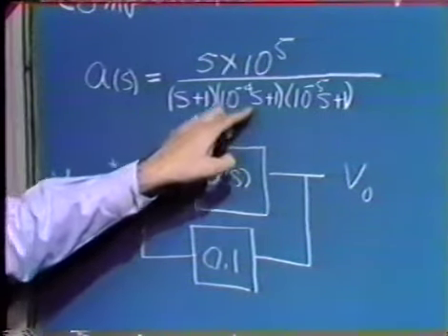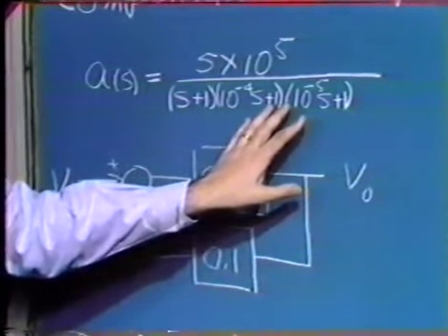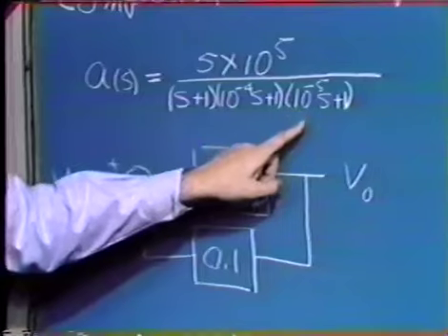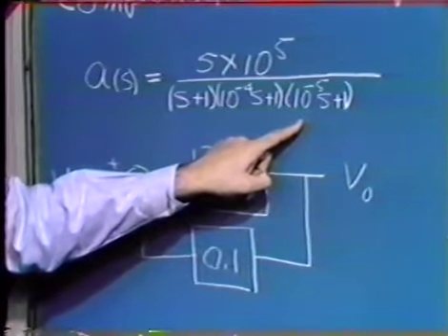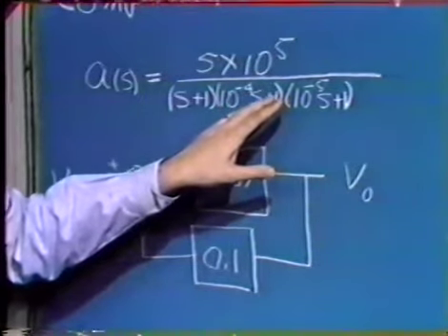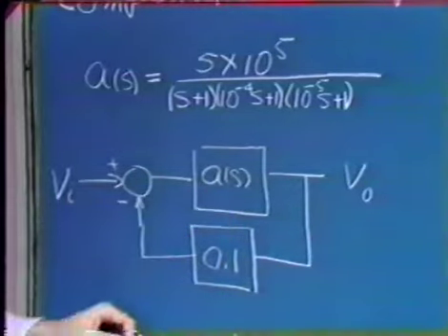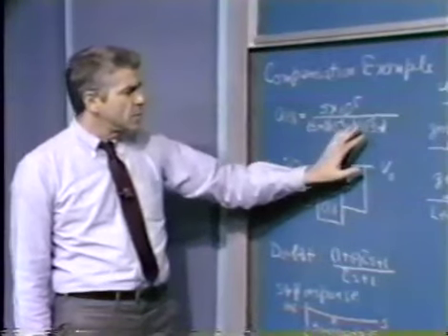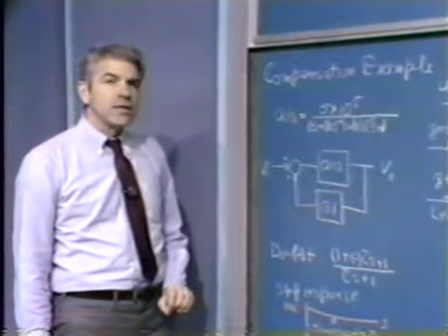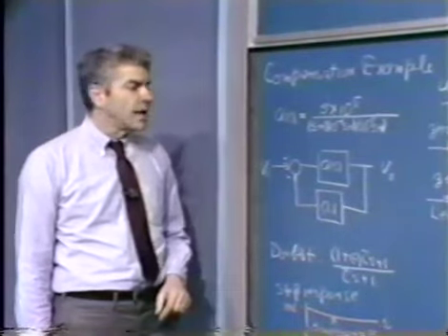However, there's then something at high frequencies that comes in that begins to deteriorate the system, and in particular gives you additional negative phase shift. It may be several additional poles, as I'm considering in this example. It may be, for example, time delays. When you look at certain kinds of transistors, you find out that they have a time delay associated with propagation of diffusion time delay. But anyway, these higher frequency dynamics give us additional negative phase shift and are ultimately the thing that prevents us from getting as high crossover frequencies as we might like to have.